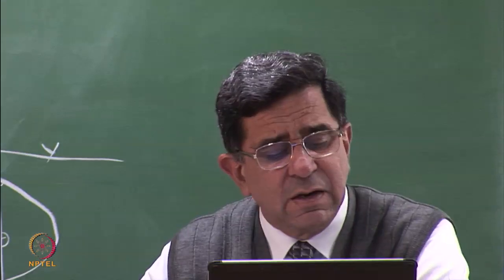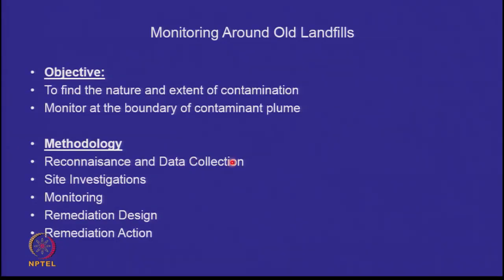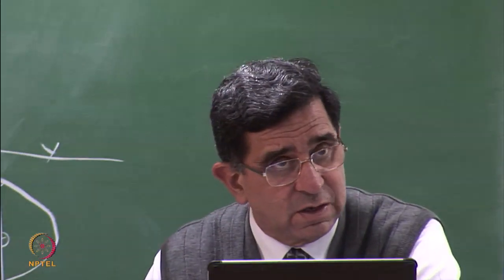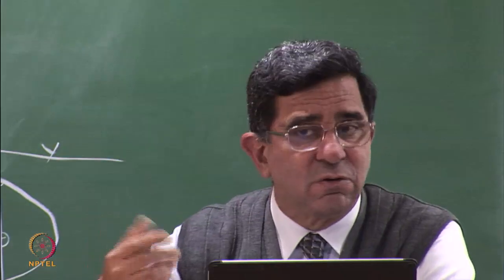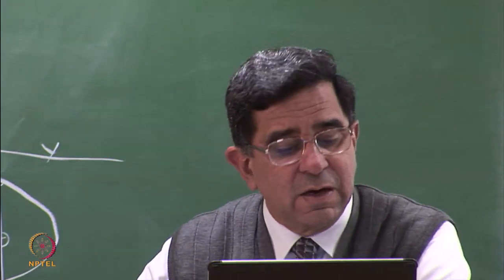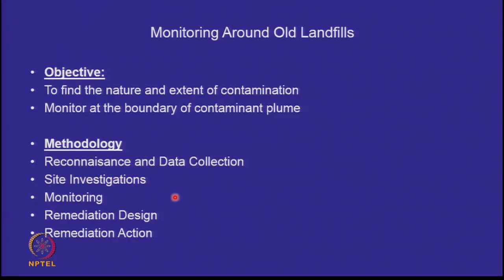So typically we will do reconnaissance and data collection. If there are some tube wells which are already there, or if there are some hand pumps in that area, you will go and pick up samples from all those areas because they're a natural source of information for you. You don't have to drill holes. Then you will conduct site investigations. And after you have conducted the site investigation, you will do monitoring. That means set up your monitoring regime.